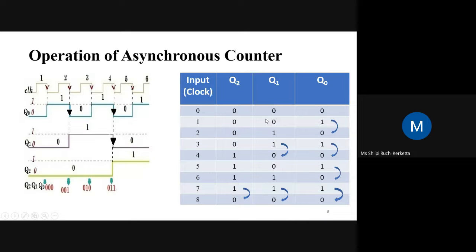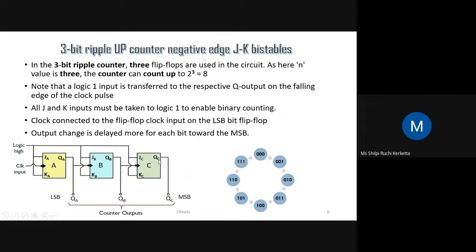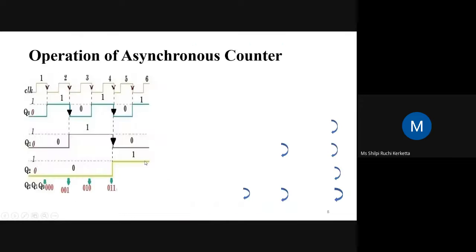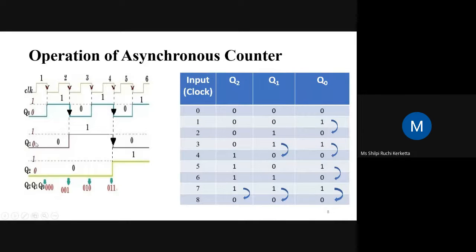That's why it is coming 2 times as 00 and 2 times as 11, then again 00 and then again 11. Okay. And if we see here for the third clock, the output is working as an input for this clock. So this is working as a clock for this flip flop. So for the third part, this is working as a clock.